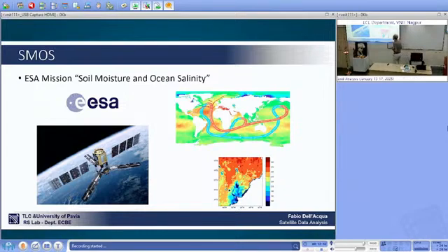So much so that generally, so this is half of Brazil. This is a part of South America. To give you an idea of the spatial resolution with which you can get this type of data, we're talking about 25 kilometers, if I remember correctly, for 1 pixel of soil moisture estimation. It's big because you need to collect radiation on a big area in order to have a decent amount of recorded power, okay, for it not to be eaten by the system noise or other sources of disturbance.